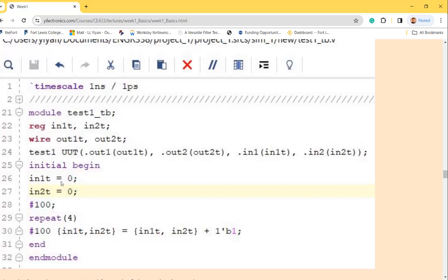If FPGA is a test bench, how do you give initial values to the ports, the inputs? You can still assign a variable to it. Actually, you can have a parameter, it's a constant. You can still assign to it, but you won't be able to change it after that. You know what I mean? So you have to assign it to something else that is changeable. But you are able to give a constant in your Verilog.